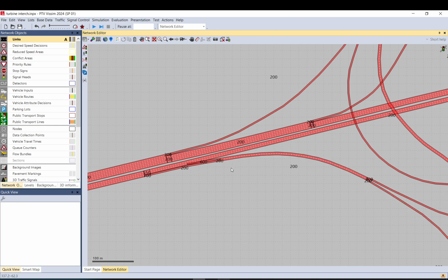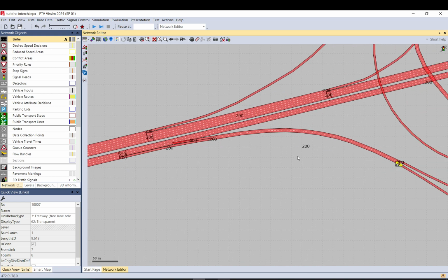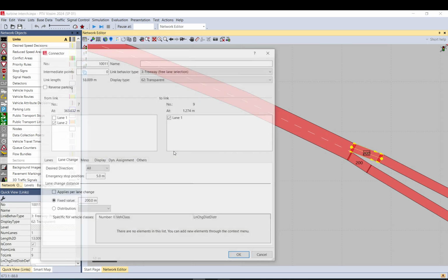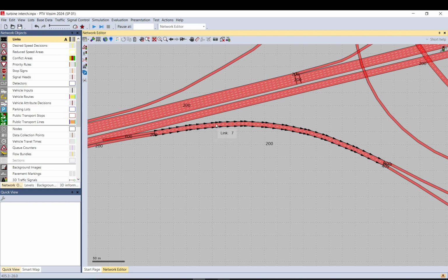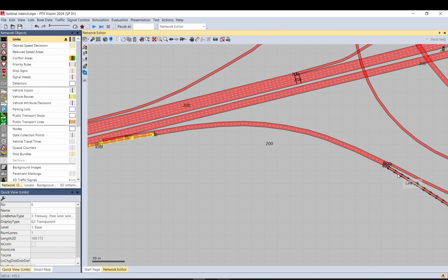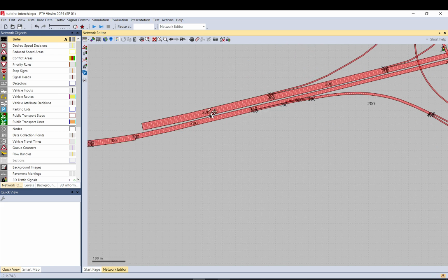Yeah, so here it's interesting because you can add a very long lane changing distance to only get out here and there. This one is 364, so you want to have it as long as this, because we will add an edge closure, so we will close the edges, so it can't happen that someone comes in this lane and then goes out there. So I will lock this so it only goes there and that only goes there. I know in real life it can happen that they go like that, but in the model you don't want that. You will end up with a huge issue. Of course, if you see that many people do that, then you need to consider it, but as a default, I'm not going to.